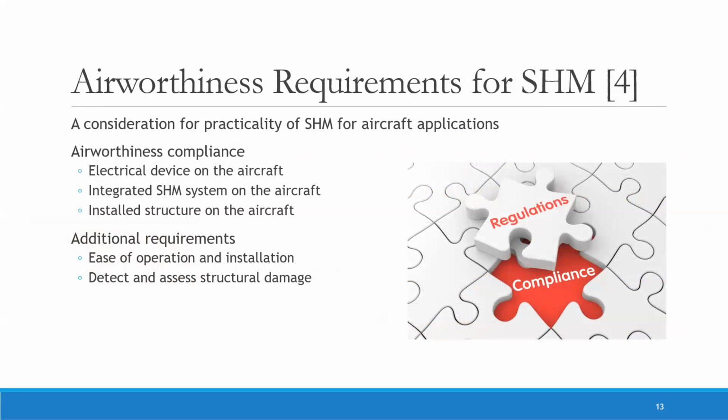Although SHM systems can be well integrated into aircraft systems, as shown by the three examples in the previous slides, the important consideration of airworthiness must be met so the systems can be considered practical for application. Since the SHM system is electrical, it must meet its respective regulations such as power supply, anti-static protection, fireproofing, radiation protection, and many more. As the system is to be integrated within the structure of the aircraft, it also shall meet electrical wiring interconnection system regulations.